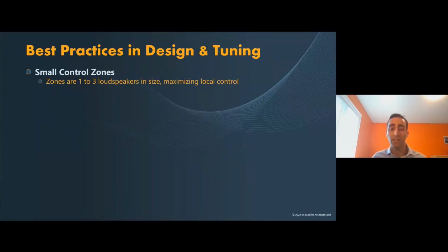However, sound masking systems are typically designed and installed in grids which are spaced at 10 to 15 feet center on center. Although this leaves small gaps, the treatment area would then be upwards of 225 square feet. But we need to tie this back to something, and our priority is always the occupant. According to literature, CoStar, NFPA, and BOMA, typical occupant density values range between 10 and 300 square foot per person, depending on the environment and its purpose.